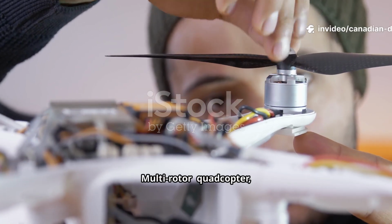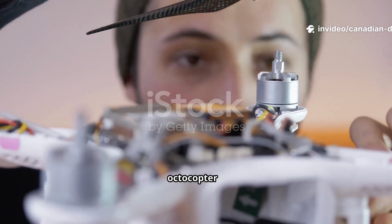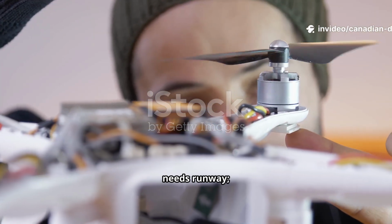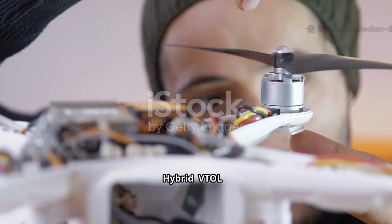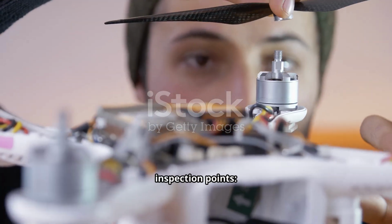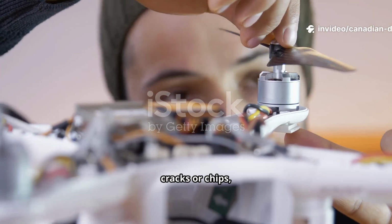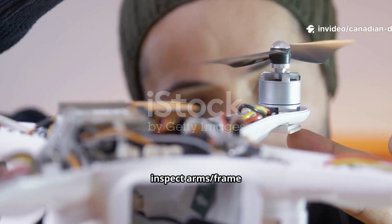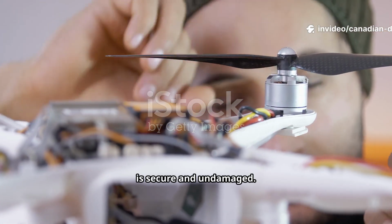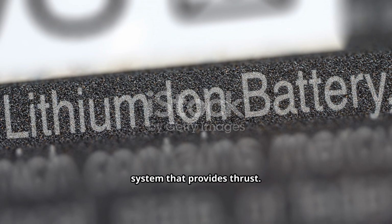Key types: multi-rotor, quadcopter, hexacopter, octocopter, redundancy benefits. Fixed wing: efficient long range, needs runway. Hybrid VTOL: combines hover and efficient forward flight. Key pre-flight inspection points: check propellers for cracks or chips, inspect arms and frame for stress fractures, ensure landing gear is secure and undamaged. Power plants, the system that provides thrust.